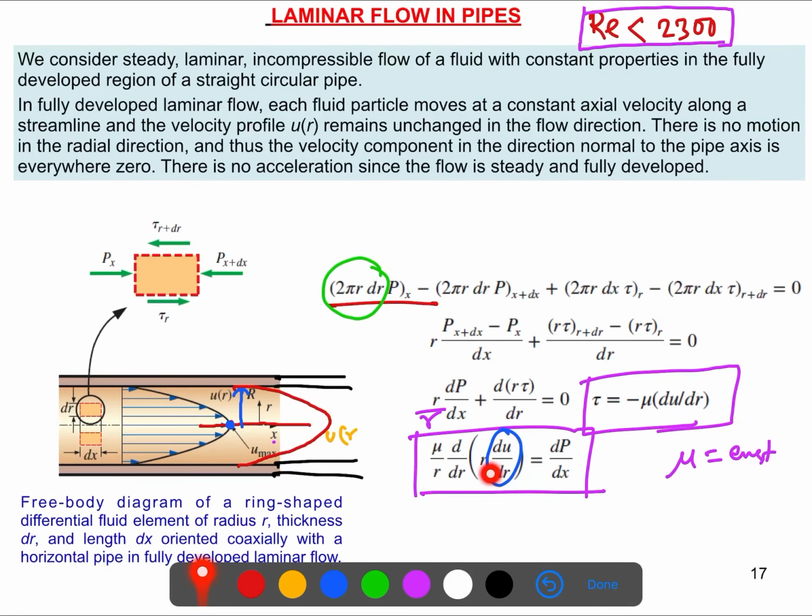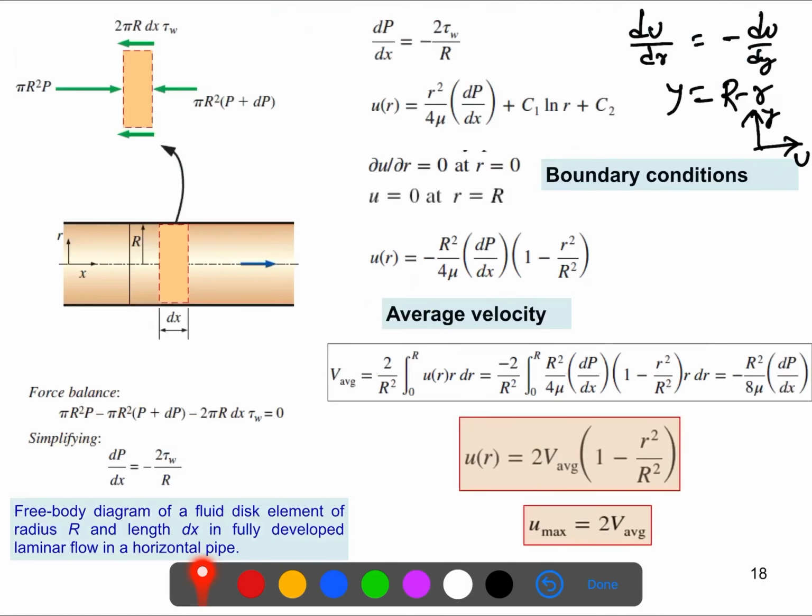just twice. If we integrate it 2 times with respect to, well, u is the variable here, the velocity. We're looking for the velocity profile u, so we integrate that twice, which means we'll get 2 constants, c1 and c2. It is a long calculation and it's not important for us, so I'm not showing it here. Here we change the boundary conditions. We solved a similar problem last week, so you can get it from there. Once you substitute all these values here, then u(r) will look like this.